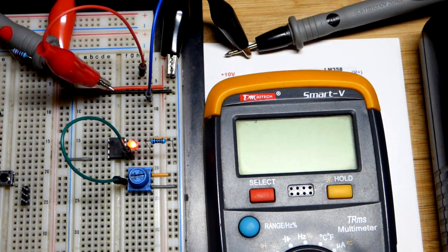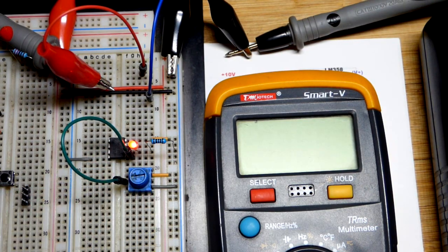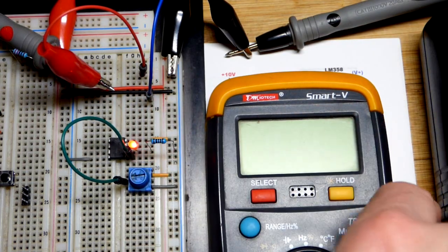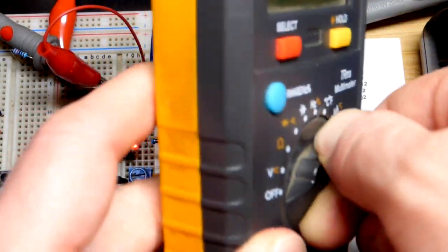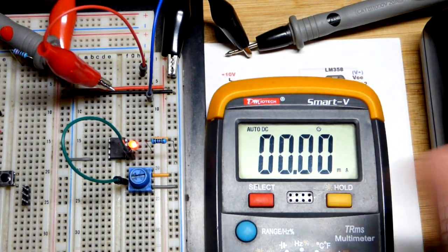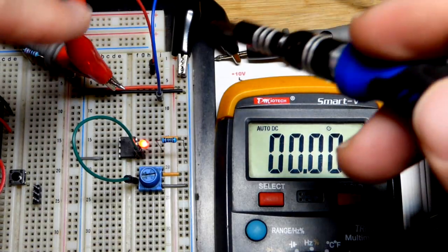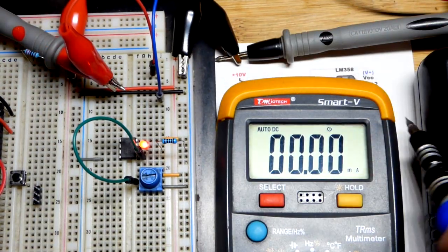So now we're going to measure current. We're going to keep it at the 5 milliamps of current, our 5 volt setting at least, right there. So very important that we're not connected to anything when we set this to measure current. The meter does not limit current, and therefore if you accidentally put it across a voltage source, too much current is going to flow. Although I did limit the current to 20 milliamps from this power supply. So it'll only be 20 milliamps even if I went to the output, and this should shut off because it sees a short circuit.